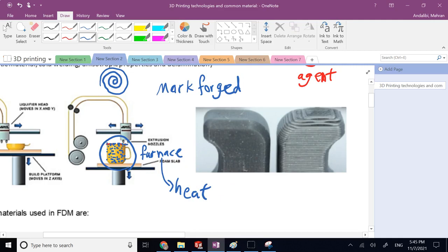Now, of course, since it's really not completely melting these particles together, or the powder, I so far have not physically tested one of the metal printed parts with this technology against one from SLM. But based on what they described to me, I'm confident that the mechanical properties of this are not going to be comparable to SLM machines. And that's one of the reasons these machines are sold at about 180K compared to those 500,000 and so on.